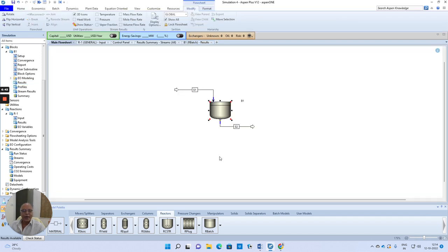Remember, the reaction is second order and the reactants are not in the stoichiometric ratio. So you need to use an appropriate kinetic equation representing conversion as a function of time for this particular second order reaction. And then evaluate what is the time required, because you will be able to calculate the necessary values from the given information. Evaluate analytically and calculate the time required. Compare it with what you have got in this simulation.